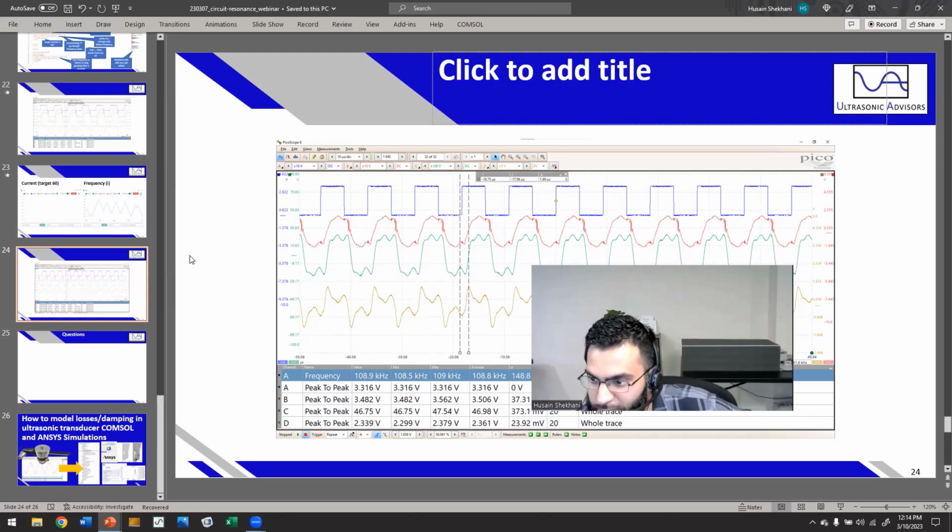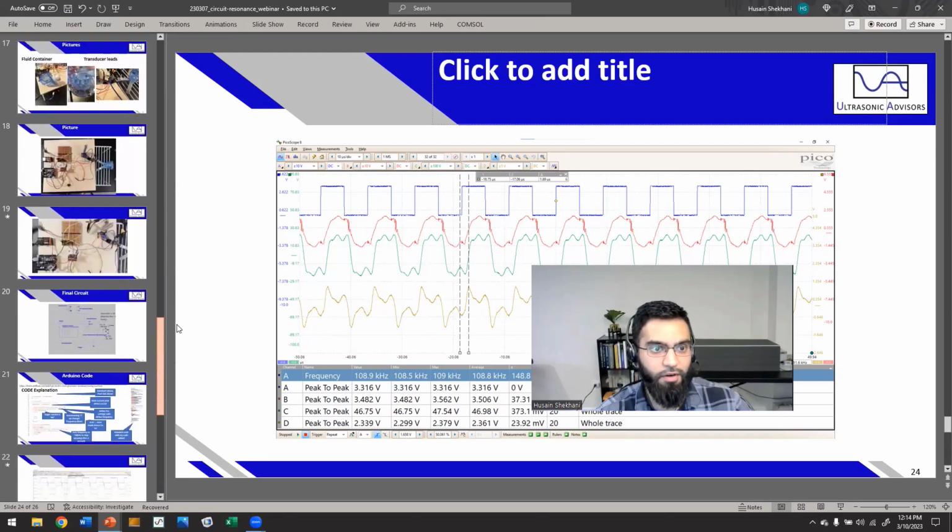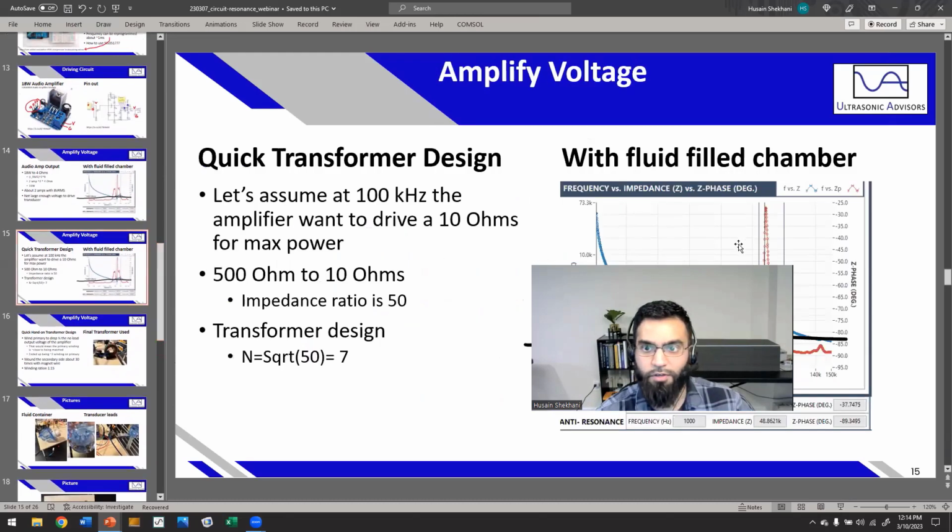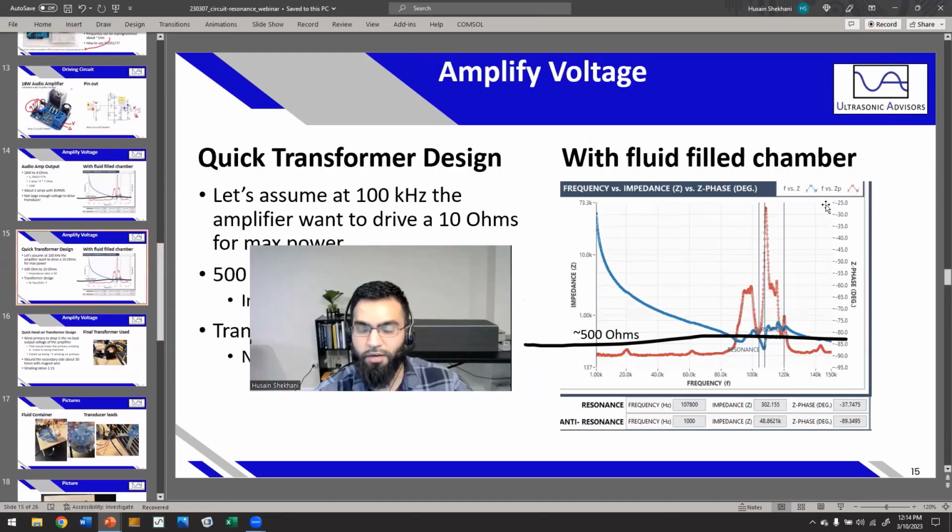Improving impedance matching using inductors, yeah, that's also good. Another thing you can do, because this load is so capacitive, like you can see the maximum phase is -25. It won't be this good when you drive with high voltage. With high voltage, the maximum phase will probably be -60. So it'll be very capacitive.